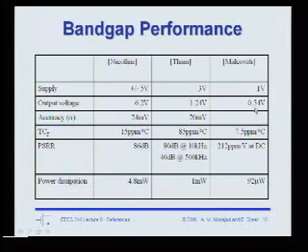Interestingly enough, I don't have an accuracy number for this one, so we don't know how accurate it is absolutely. But if we compare these accuracies, this second reference is 20 millivolt accurate, but only an output voltage of a band gap, whereas this one is 24 millivolts over several band gaps. So definitely 5 band gaps. So this circuit is actually much more accurate in that sense, right?